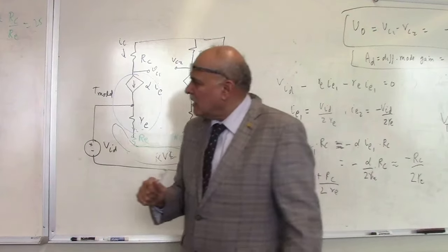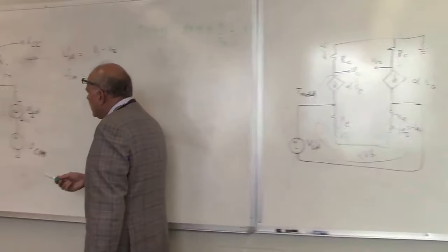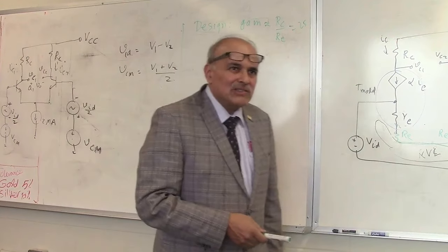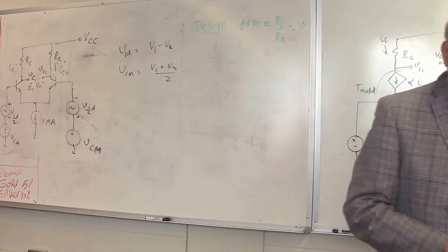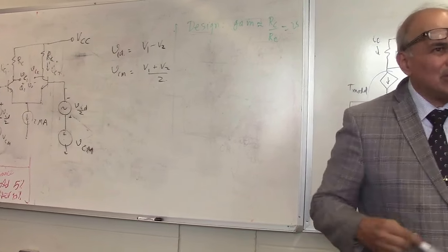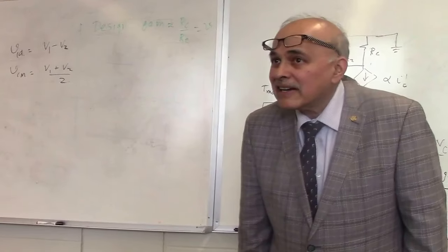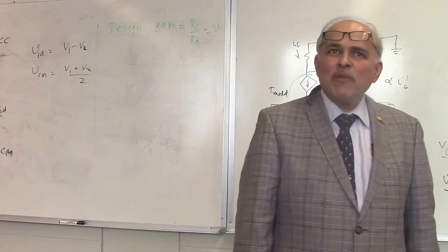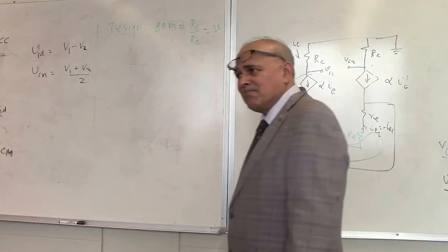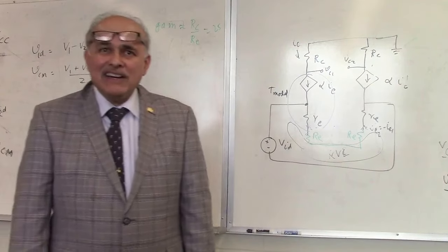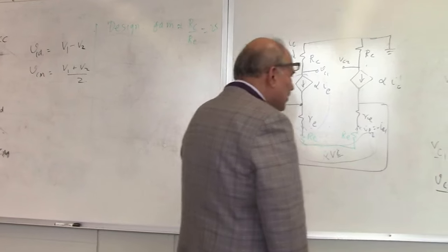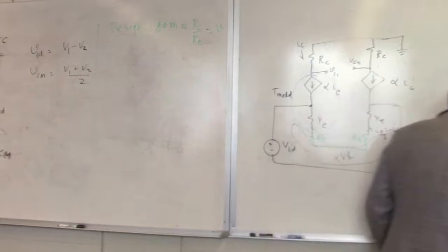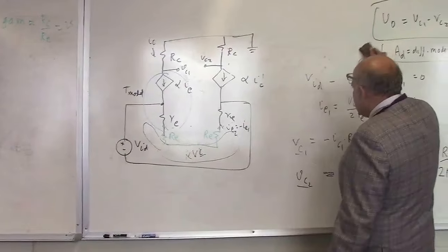But now, look at this circuit here. We had a 2 milliamp current source. How the heck do we get a 2 milliamp current source? In fact, the paper says don't use a 2 milliamp current. So how do you make a current source? Voltage and resistance. Correct. That is a crude and sloppy and very effective way of making a current source. Okay. So, you know, a current source, what is the resistance of a current source? Large, right? So if I just take a voltage, can I erase this all here now? Okay.